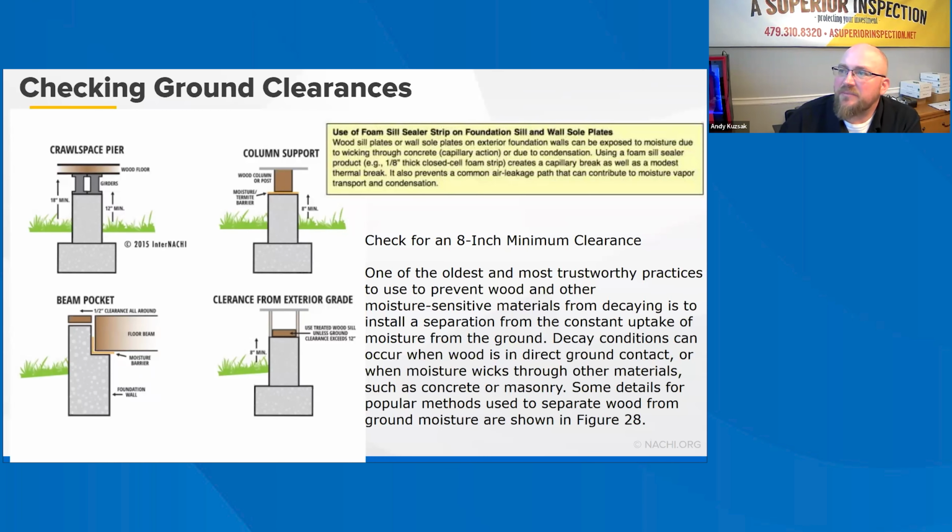Decay of common wood framing materials can begin when moisture content of untreated wood exceeds 20%. In foundation and building applications, these conditions should be avoided by adherence to minimum ground clearances and detailing requirements. The ground clearances outlined in this section are considered minimums that have worked reasonably well in typical climates. In climates with frequent rainfall or sites with continuously moist ground conditions, greater clearances are recommended. In addition, capillary breaks are important, particularly when clearances are at minimums. Capillary breaks help protect wood from wicking up moisture from the foundation, around the foundation from the ground.